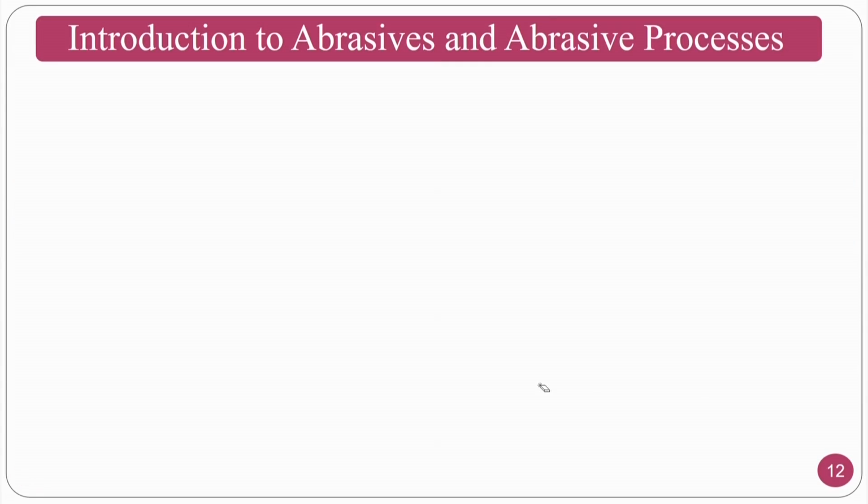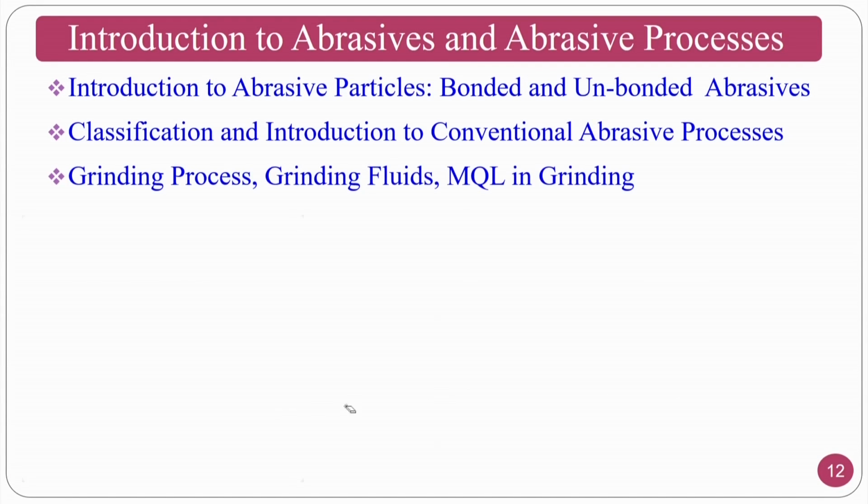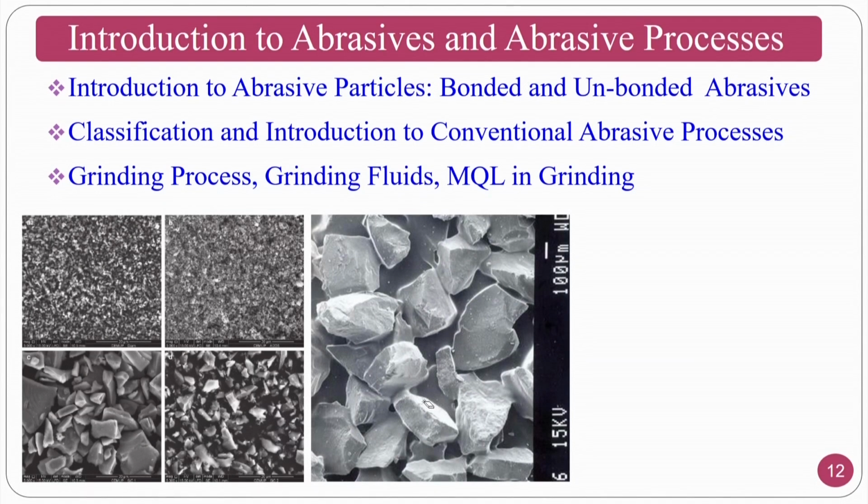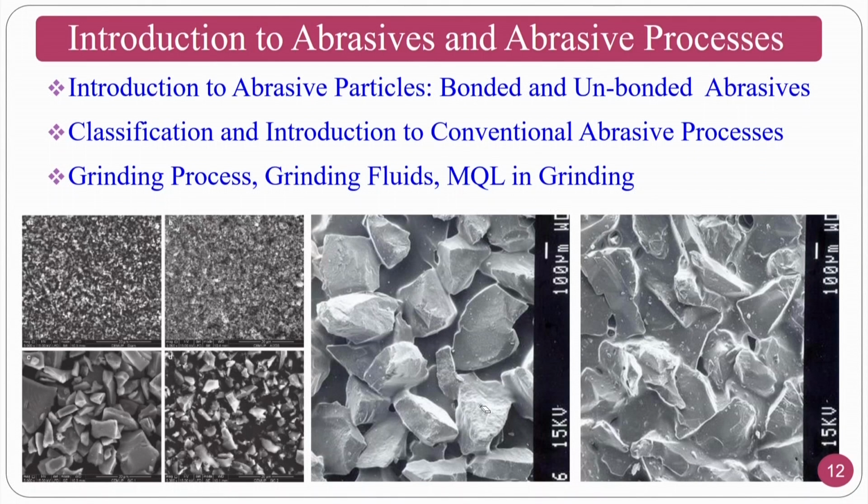So we will see what we have studied in detail. We have seen the abrasive particle sizes and how to convert the size of the abrasive particles from the mesh size, and we have seen also the bonded abrasives. What do you mean by coated abrasives? In some of the cases the people will coat. So the abrasives are brazed to the grinding wheel or brazed to a wire, then on top of it they will give the coating also, that we have seen.